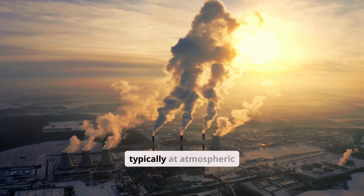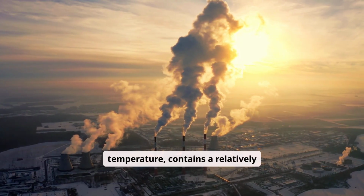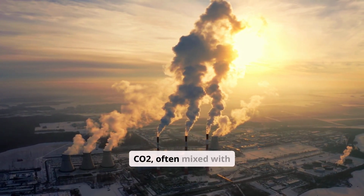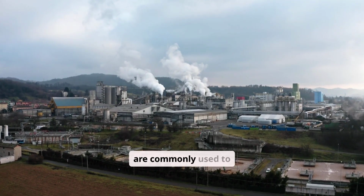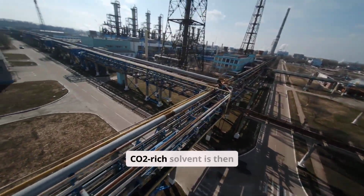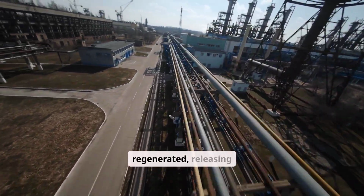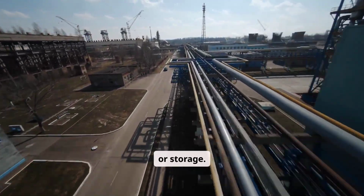The flue gas, typically at atmospheric pressure and moderate temperature, contains a relatively low concentration of CO2, often mixed with nitrogen and other gases. Amine-based solvents are commonly used to selectively absorb CO2 from this gas stream. The CO2-rich solvent is then regenerated, releasing a concentrated stream of CO2 for utilization or storage.